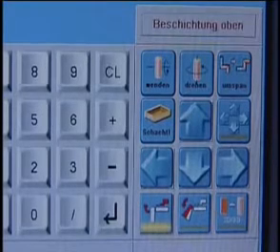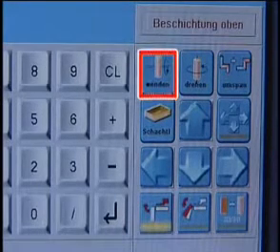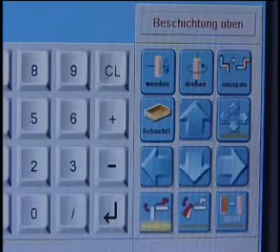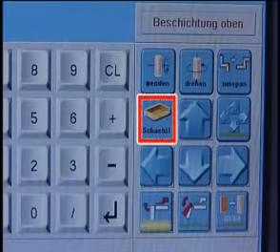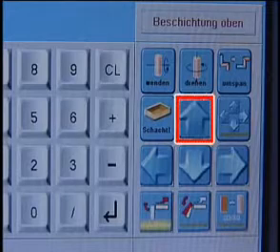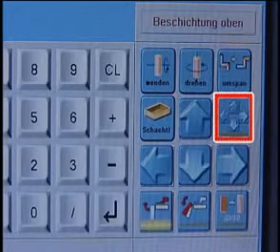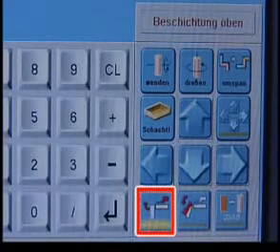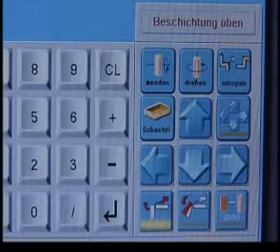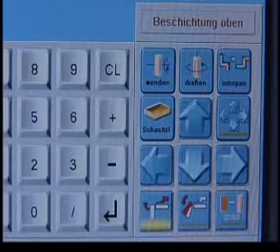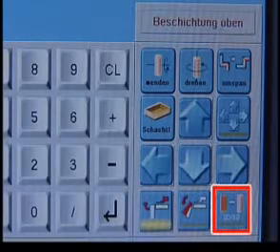In the first row, you will find the buttons for material handling, like turn, rotate, and reclamp element. In the second row, there is the submenu for boxes to bend a part on all 4 sides, the cursor up button, and the button to activate the scroll function. The fourth row starts with the power mode button to modify the speed of the folding beam, step bending to form radius, and the button to switch between 2 or 3-dimensional.